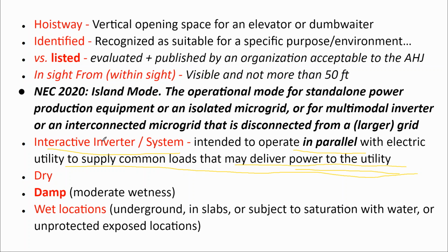There are one-way inverters that don't, at that point of interconnection to the grid, feed any power out of that point. It might just be a one-way charger, and the inverter might have a separate output somewhere else for feeding a critical load panel. Like a UPS system, a battery system that protects your computers when the power goes out, that's a one-way inverter that charges from the grid but has a separate output.